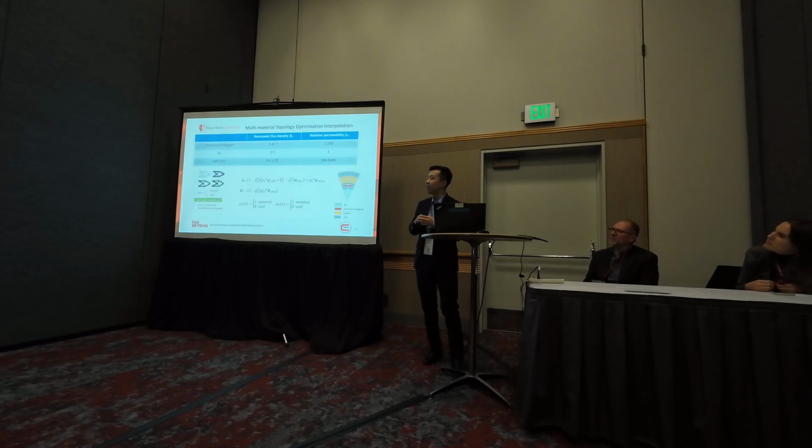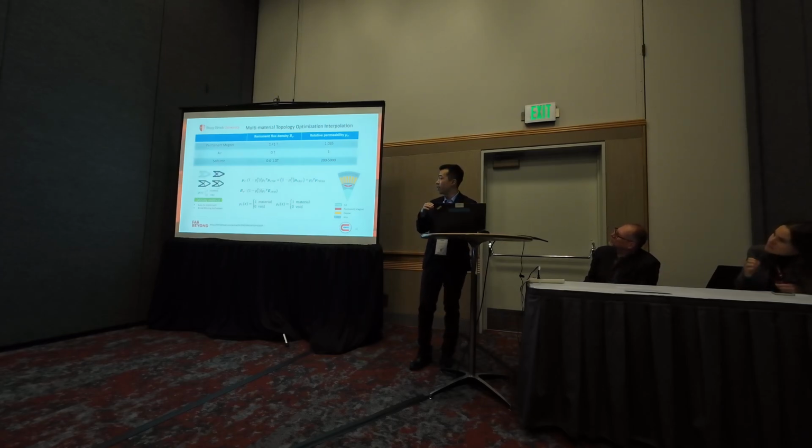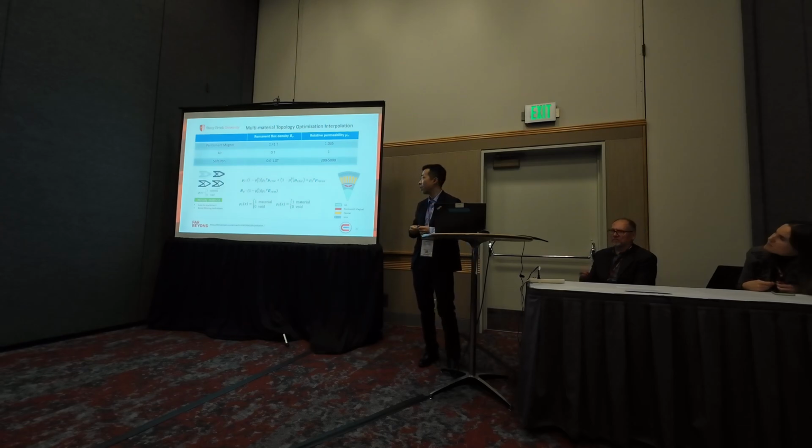And the remnant flux density means the level of magnetic flux density that remains in the magnetic material after the external magnetization has been removed. For example, if a material has higher Br, it will be hard to magnetize and demagnetize. For soft iron, they have lower Br, which means it's easy to magnetize and demagnetize.